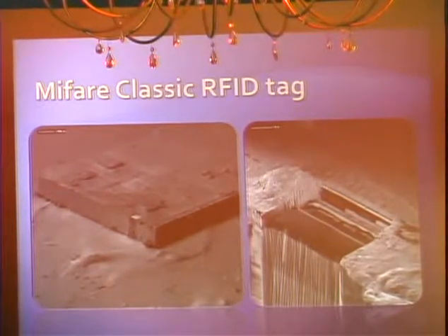Now, to get to these transistors, or the wires before the transistors, we need to slice the chip. We need to take away layer by layer by layer and take pictures of those metal wires and transistors. Now, we were asked a number of times what type of laser we use or how expensive our focused ion beam is and all that. We don't need any of that. So these pictures were taken with an electron microscope, but you clearly don't need an electron microscope to do any reversing. I mean, these pictures, other than looking cool, have had no effect on our project whatsoever.